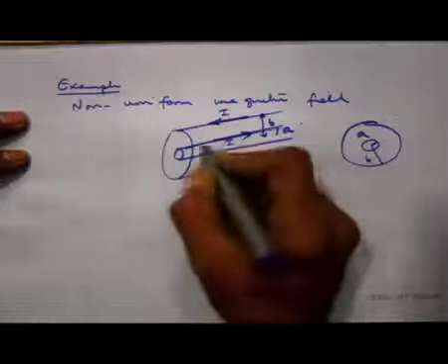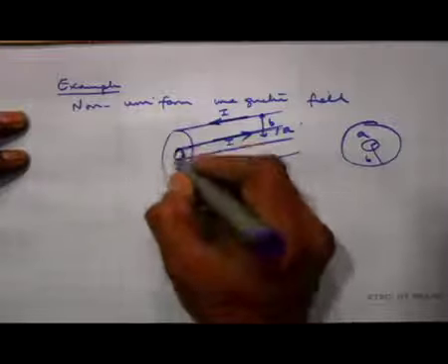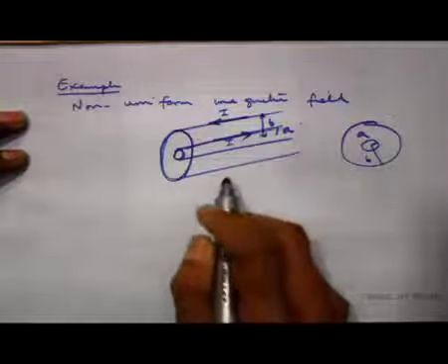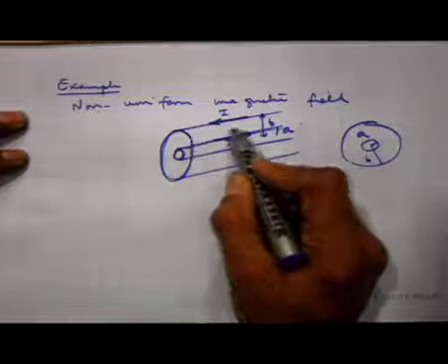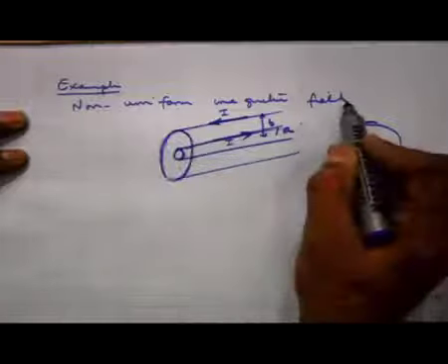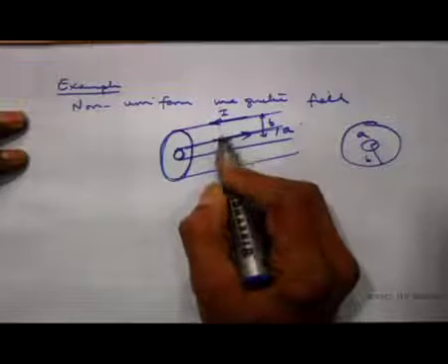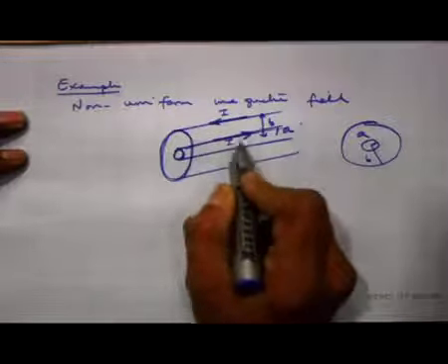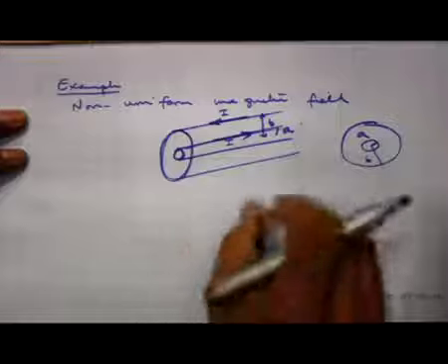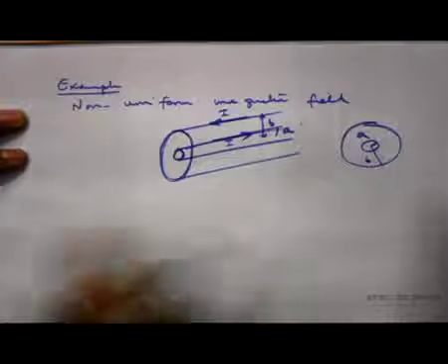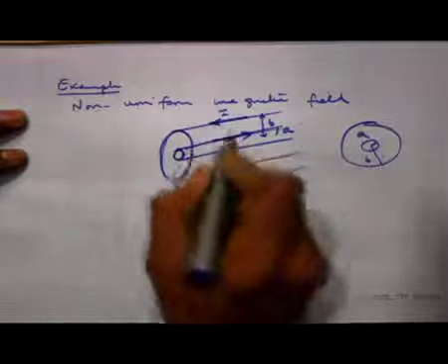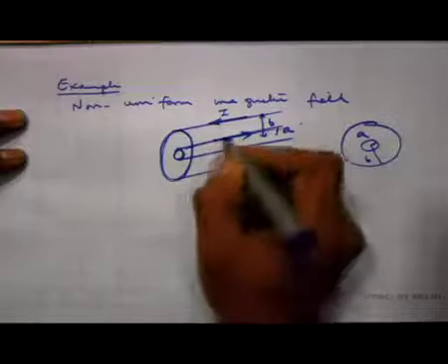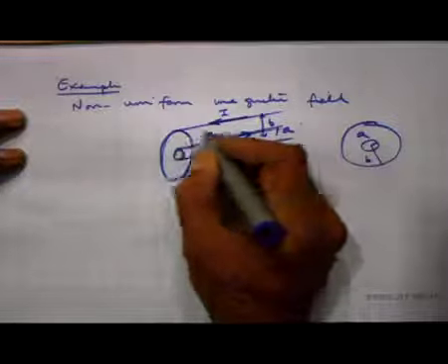So, for all this I need to calculate the magnetic field in the system. Now, this is a surface current propagating through the outer surface of this inner conductor and the inner surface of the outer conductor here. First thing you can notice is because of symmetry, magnetic field will not be dependent on the position along the length of the conductors. Magnetic field cannot have a radial component. Magnetic field has to be azimuthal, just like in earlier examples. When you take a long, infinitely long conductor, it creates a magnetic field which is azimuthal, which is circulating around the conductor carrying current.